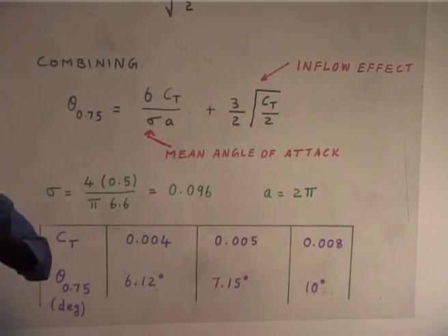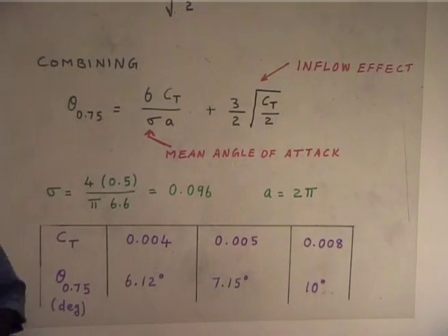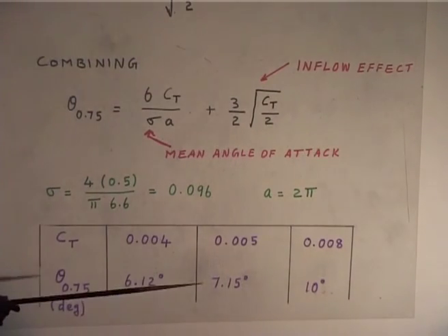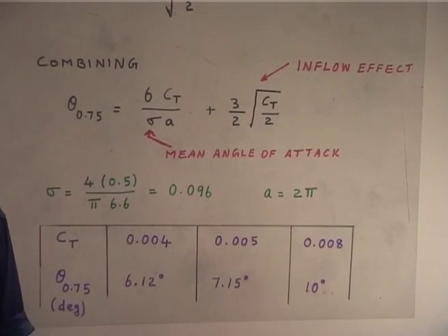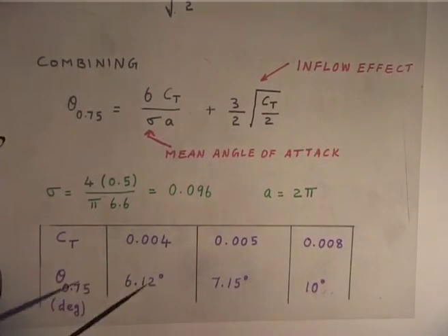Now, in preliminary design, you do not go and make a high operational angle, because when you build it, it may be still more, and you may start having blade stall, more drag, more power. So, you try to operate always around 5-6 degrees, but the actual calculation will go about 8-9 degrees in the hover case. That is a detailed calculation I have.